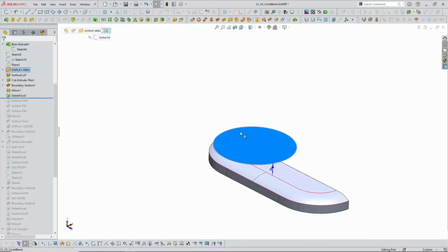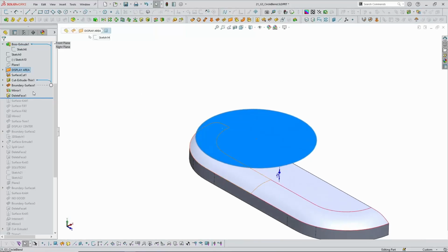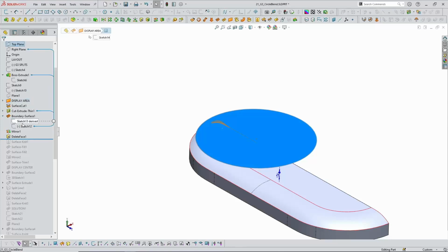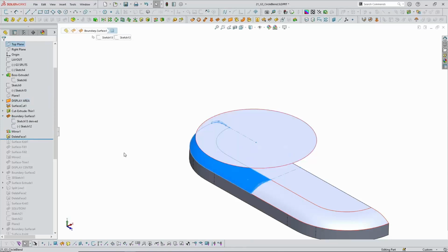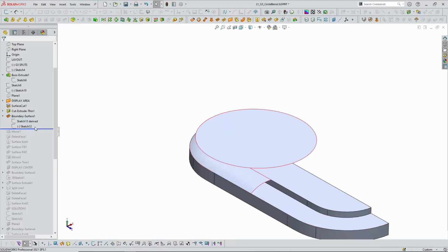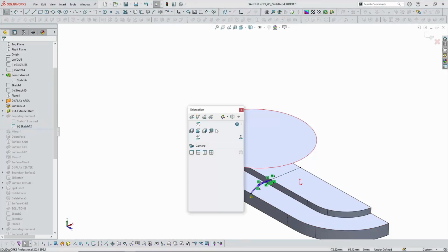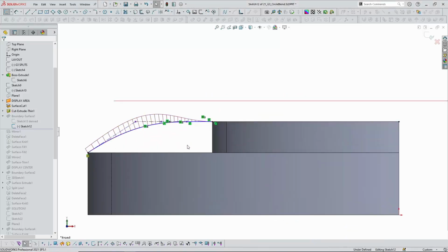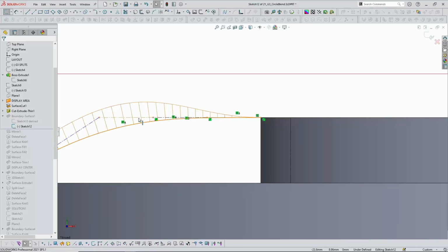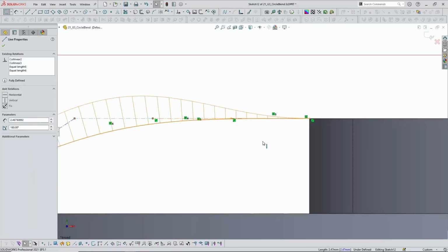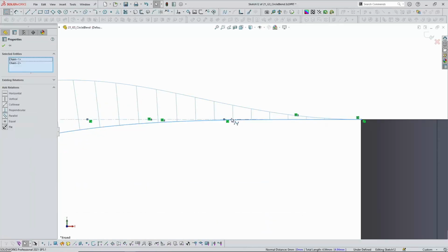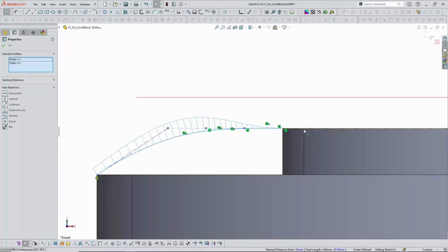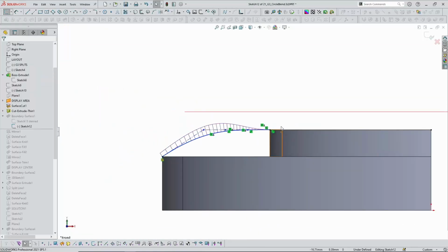So I have my planar surface I'm creating here, but before we get into the final blend, we'll look at this pillow shape. The pillow shape is created with two sketches, but it's actually being defined by a single sketch, even though they're on different planes. So here I have a style spline. I was talking about those three different control segments required. So I do have three control segments. They've been made collinear to this model edge, and I have that smooth, seamless acceleration of the G3 curve.